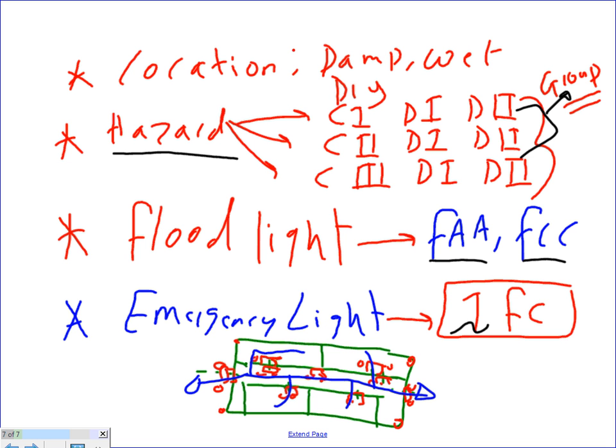We didn't do emergency calculation with Visual. You can take, say, a 6 foot path here and make a calculation zone and maintain an average of 1 foot candle using a bug eye. We haven't done that. Any question, guys, about these considerations when you put in a commercial or industrial building, especially industrial buildings for hazardous locations? Any question about these?